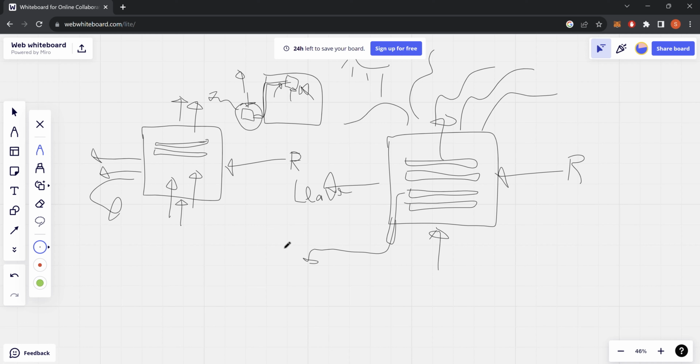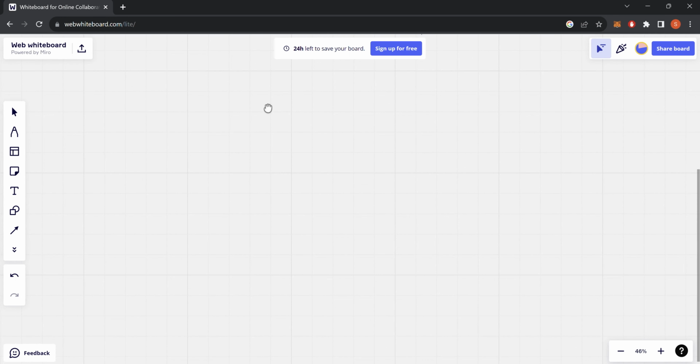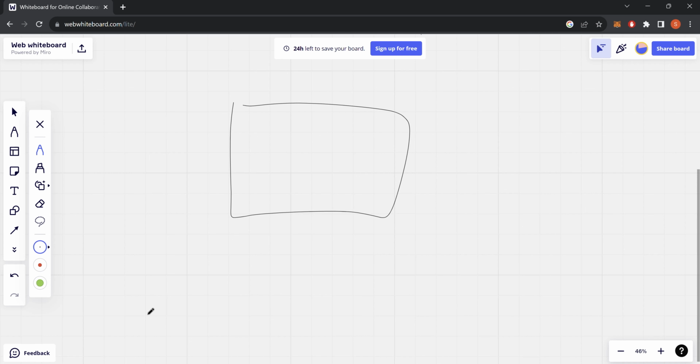Now there's ductless as well. And the way ductless works is the same premise of heat transfer, but let's use a house with 2 rooms, for example. This is a floor plan view. I got a ductless unit here and a ductless unit here. And I may have a tiny condenser over here, or a tiny condenser over here, or maybe I have one condenser that runs both of them. That's totally possible. But basically that condenser is going to run those refrigerant lines in a loop up your walls in much smaller lines up to the box unit.